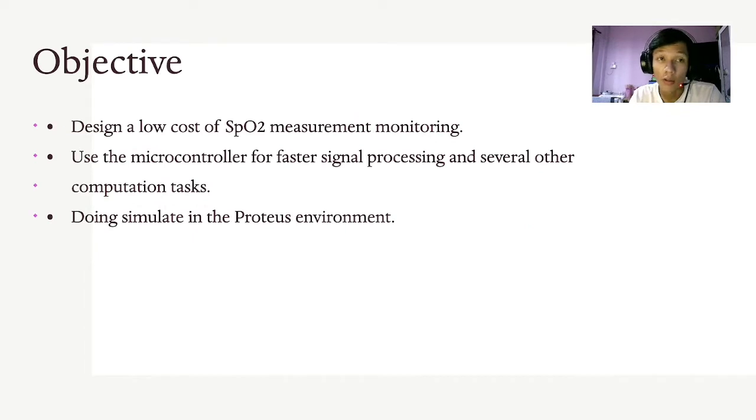So next, the oxygen saturation level is the most common medical data used to understand the patient's condition. The next is our objective for this project. Firstly, we design a low-cost SpO2 monitoring system. Second, we use the microcontroller for faster signal processing and several other computation tasks. And the third point is doing the simulation in the Proteus environment. So our main objective of this project is to develop an automated and low-cost oxygen saturation measurement system that will assist and support doctors in monitoring the patient's condition.